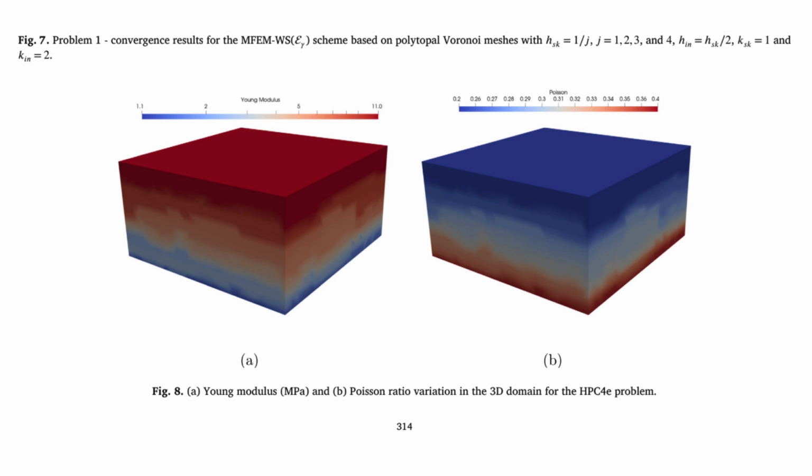This coarse parameter, gamma, controls how accurately we calculate the traction, that's the normal force component, across these boundaries. Okay, so the coarse scale handles the interfaces. What about the fine scale, gamma? That governs how refined the calculations are inside each individual polyhedral block. So you have a coarse view of the connections and a potentially much finer view of what's happening locally within each piece. Right.